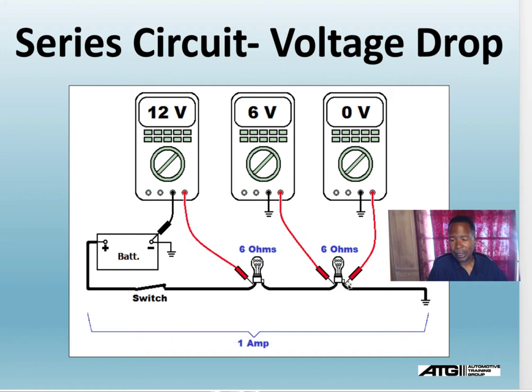That means on this end here, I should be near 0. Should be no voltage. It should never be voltage on the ground side. It should never be anything higher than 0.1 on the ground.